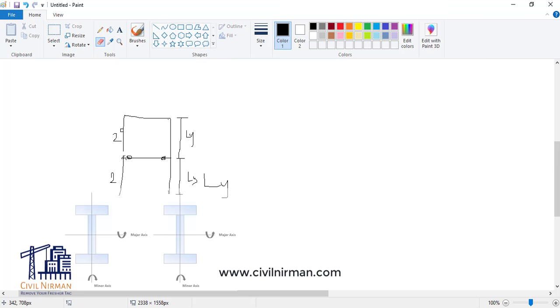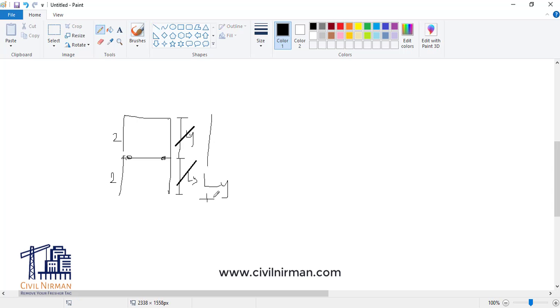In shear connection, this entire column will move in the direction of the applied load. So when there is no brace and there's a normal shear connection, then instead of providing individual lengths, we will have the entire 4 meter as our Ly.